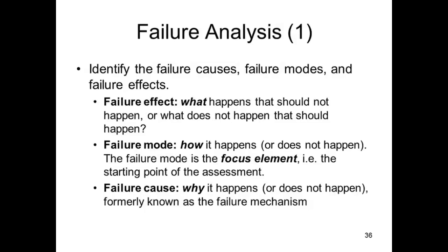Something I'm hoping to do here, by the way, is to put some of the terminology in the AIAG VDA FMEA manual and make it somewhat more understandable in terms of an actual example and how it's actually supposed to be used. So when they say focus element, it simply means this is the starting point of the assessment. We don't start with the failure effect or the failure cause. We start with the failure mode. In this case, the worker forgets to check the torque. That's the starting point.